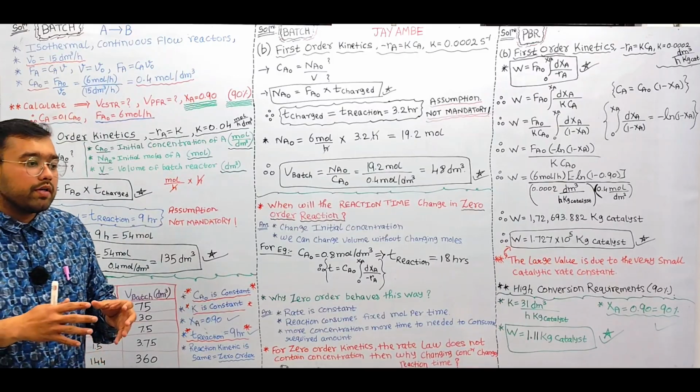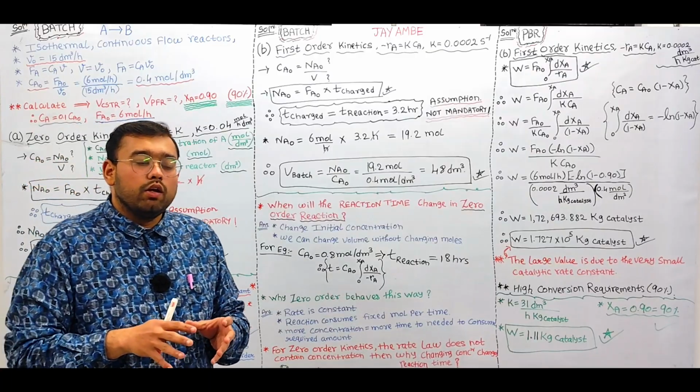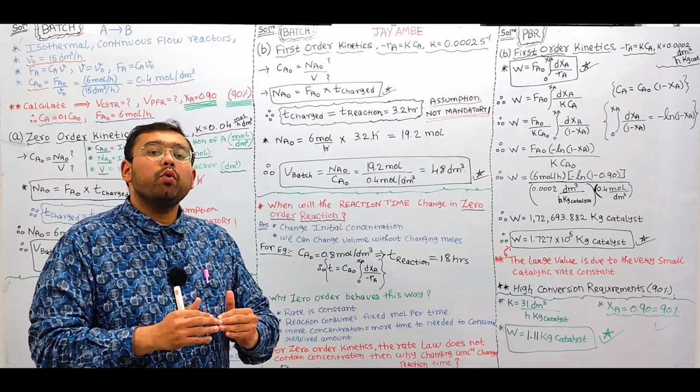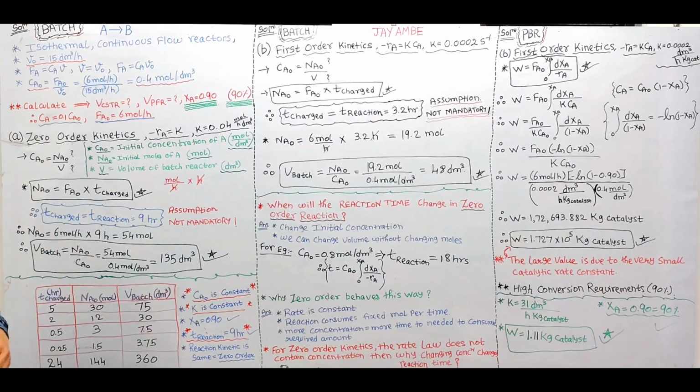If the pump feeds at a very low rate, it will take more time to fill the entire batch reactor volume. So the charge time depends upon the availability of good operating pump systems, and it is not mandatory that it is equivalent to the reaction time.